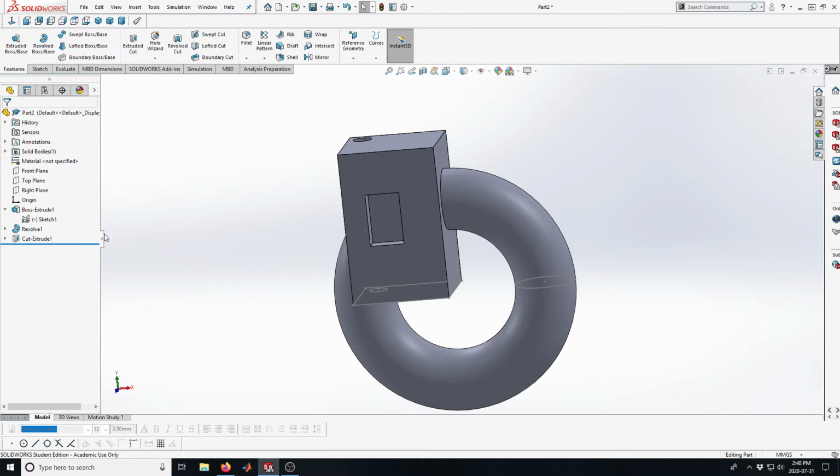So in terms of making parts, what you'll do is you'll build up this feature tree to get every successive feature that you add or cut from the part, and it'll show you the history of how you created the part. Now, really good designers, really good CAD users will have a fairly short sequence of features, basically trying to make a complicated thing using as simple elements or simple geometry as possible.